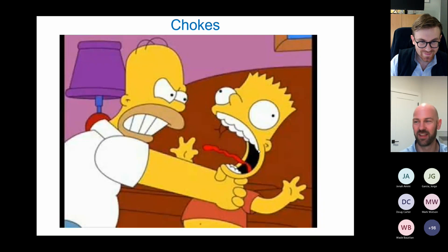Okay, chokes. We're really going to hopefully be implementing both wellhead chokes and bottom hole chokes to predict pressure loss through them. Now, for a bottom hole choke, it seems like it would make a lot of sense to consider liquid loading as well, because upstream of the choke we've got high pressure, and then downstream of the choke we have a lot lower pressure. And so the velocities are changing. So I think we'll be considering liquid loading, critical velocities needed to lift both kinds of liquids, water and condensate, on both sides of the choke. So this will be coming, and hopefully it's something you guys want.